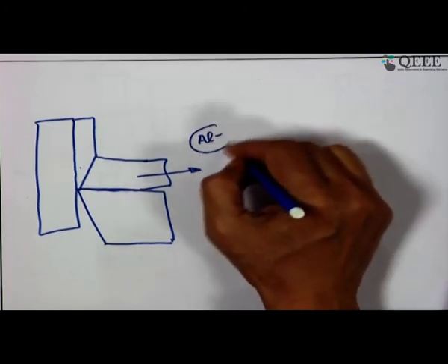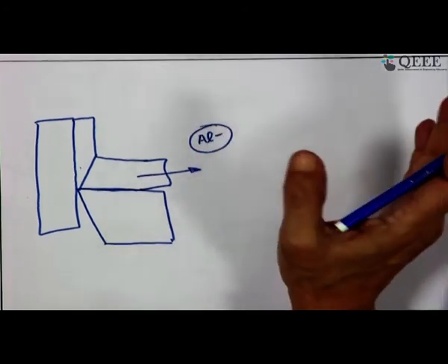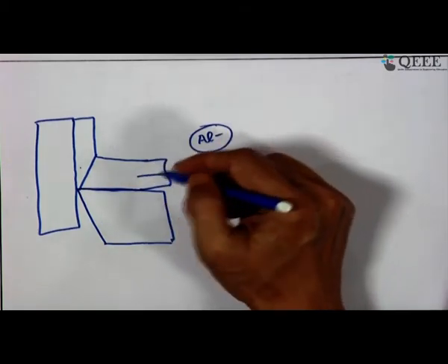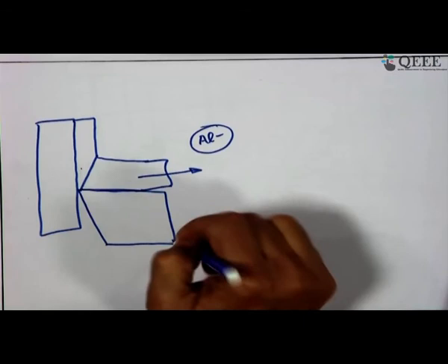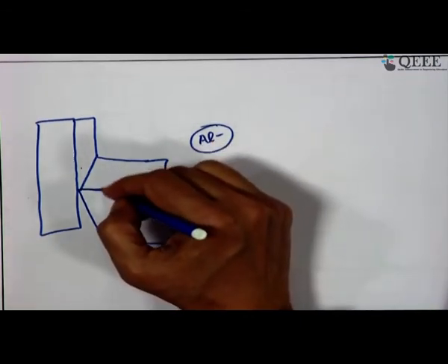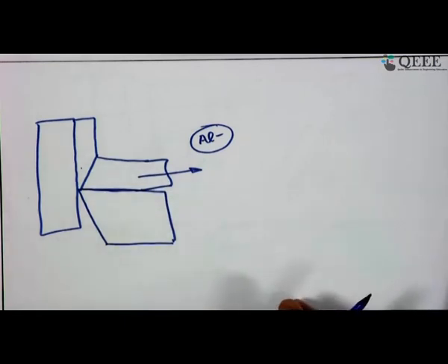Aluminum, titanium or calcium are used for deoxidation of steel, and research has established that aluminum can come over here and put a layer of aluminum oxide, and this layer can prevent crater wear sizably. So, this way the work material can also be a factor which prevents wear on the cutting tool.